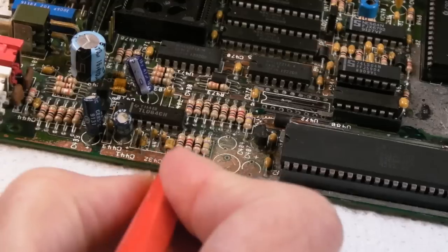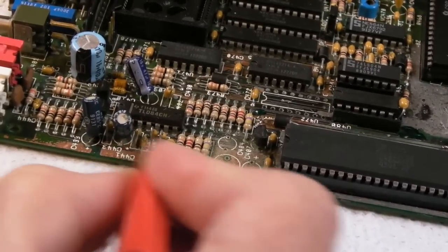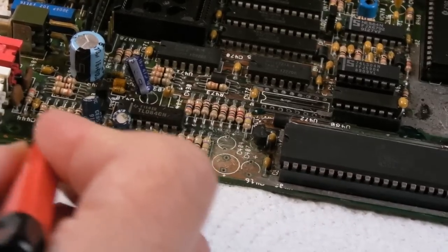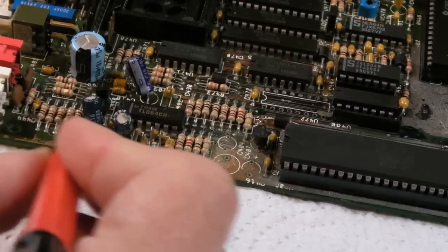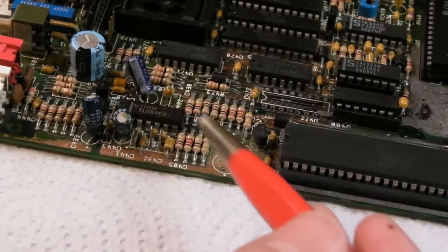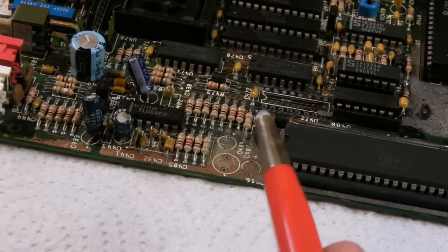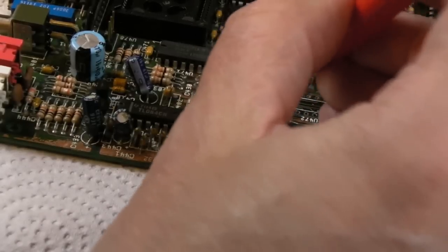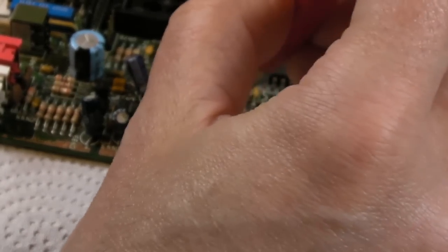But anyway, you'll be able to see, it will look an awful lot cleaner. Now I'm able to get access to a lot of the things around here, clean up the flakes of solder mask paint, get some vinegar on it, a couple of cycles of vinegar and stuff cleaned pretty thoroughly around here. I will block the odd via where I can see corrosion on the other side. In other words, it's gone into the via, it's corroded the via. Those will get blocked, and then it should be alright. The chances of one of these traces going open circuit at some point is going to be slim to none once it's been cleaned.